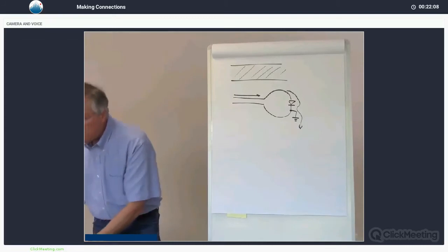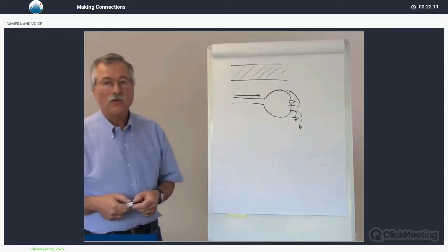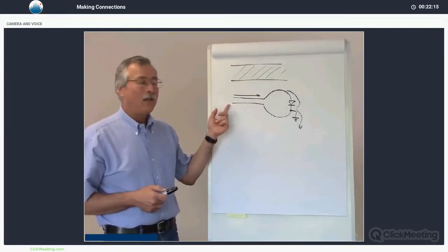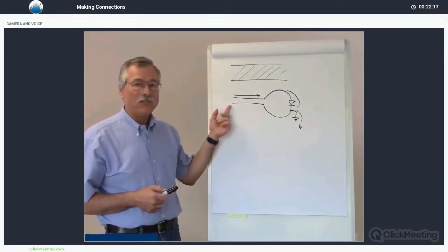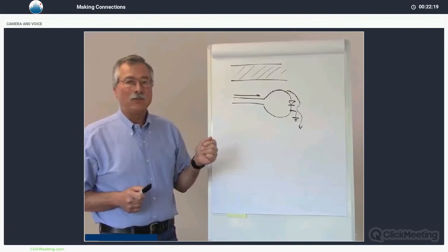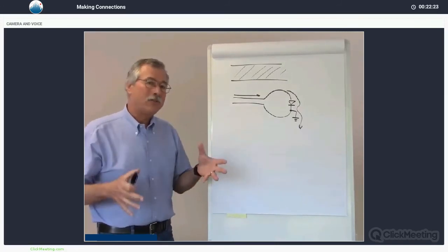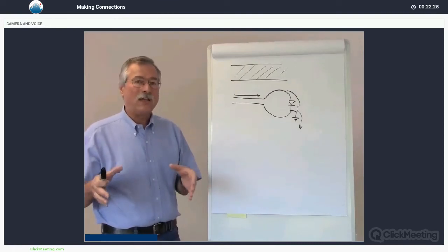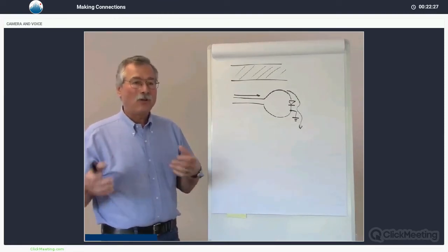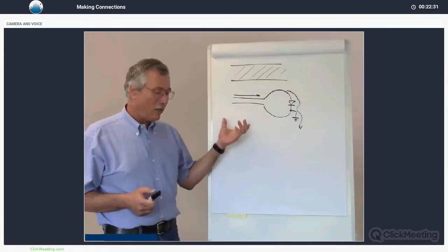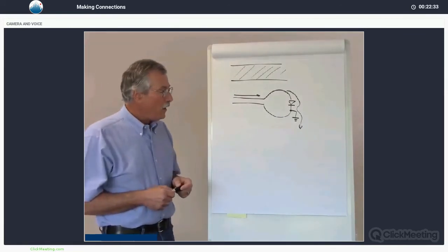What we don't necessarily want to do is look at the voltage across the laser diode, because we're looking at a current source, and the current source voltage can vary wildly depending on what the load is. A laser diode has a curve to it, an IV curve. The voltage is going to be kind of squirrely, trying to drive that thing with a constant current. So consequently, a voltage impression is not as important as the current.